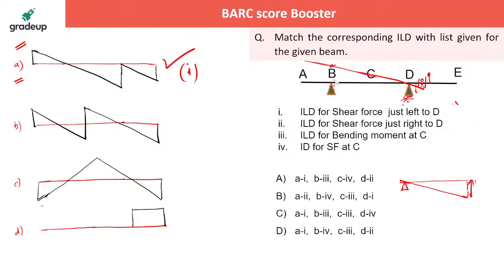Hence you cannot expect that. What are the other possibilities? The other possibility is that if you are bringing it down, it may come like this. But it is once again a curve. For a determinate structure, one cannot expect a curved portion. So it is not possible. Are you getting my point? It is not possible. So what will happen? A complete upward movement will occur at this location. A complete one unit displacement will occur at this location.